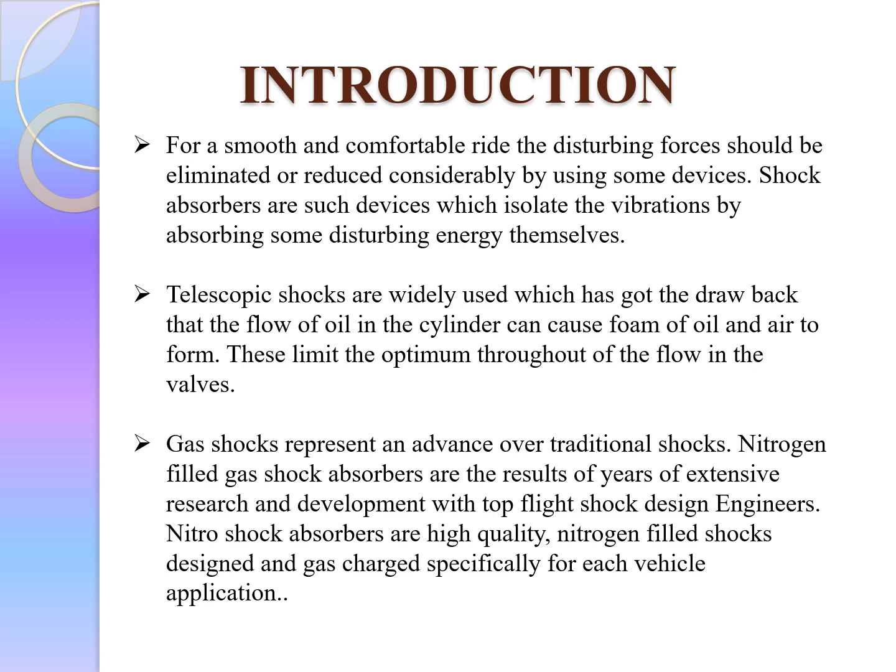Next, coming to the introduction part of the need for shock absorbers. Basically, a shock absorber is a hydraulic damping mechanism for controlling spring vibrations, and it controls spring movements in both directions, when the spring is compressed and when it is extended. The amount of resistance needed in each direction is determined by the type of vehicle, the type of suspension, the location of the shock absorber in the suspension system, and the position in which it is mounted.